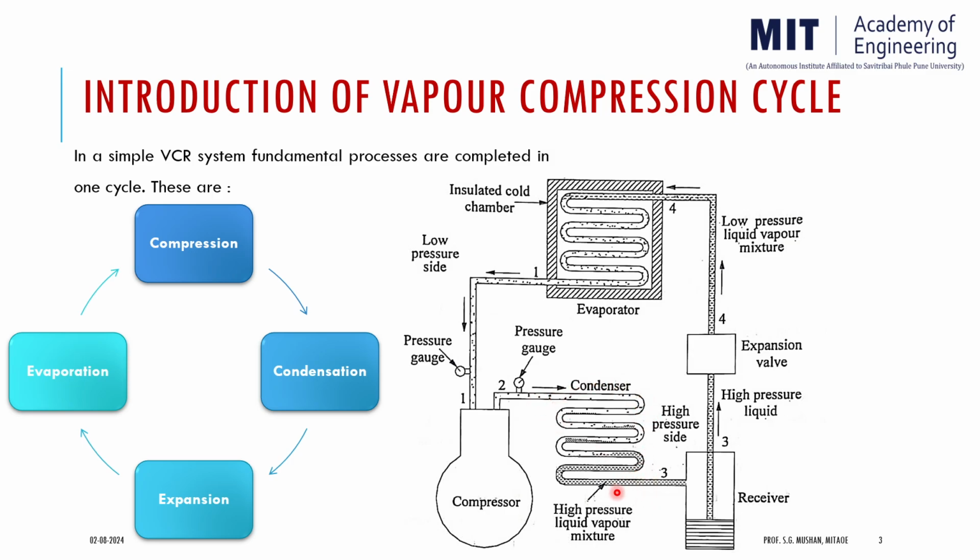So here the condensation process can be water cooled or air cooled. Depending upon the situation, the type of condensation can be opted. As soon as the high pressure, high temperature refrigerant enters the condenser, it starts changing its phase to liquid state. And this condensation process will take place at constant pressure and temperature. Means there will be no change in the pressure or temperature.